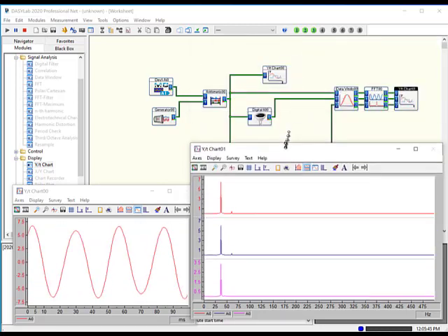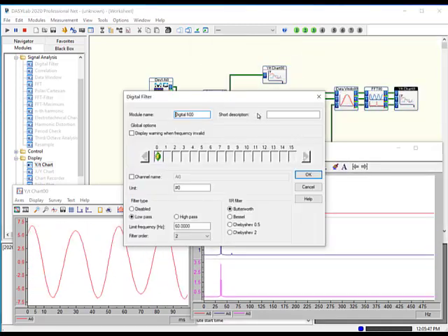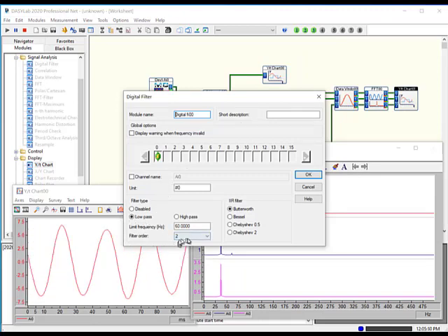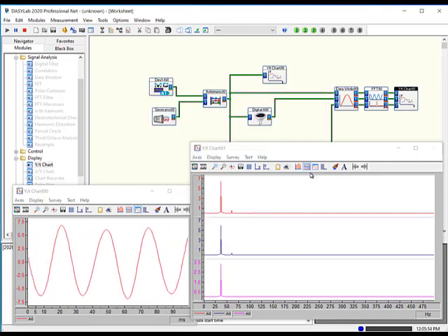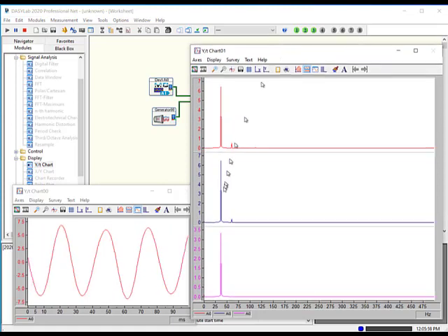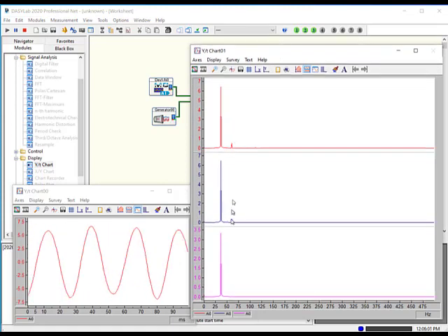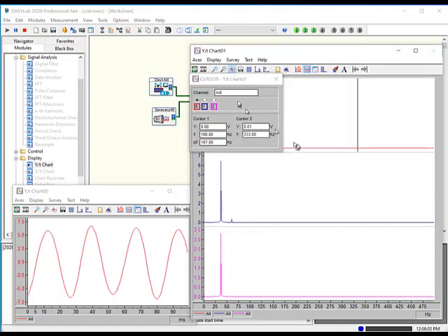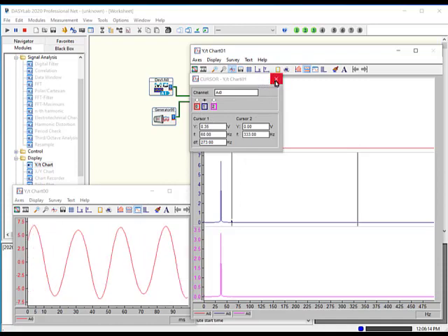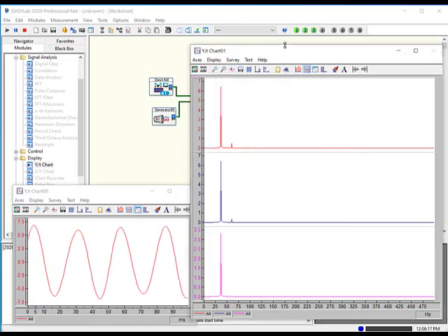One of the things you can do while you're running is modify the digital filter. So it's a low pass filter. I'm going to make it a stronger filter by going all the way to a filter order of 10. And when you do that, you can see that there's still some energy left from the 60 cycle signal. Look at this with the data window. The amplitude is not much diminished from the data that we're generating. So filtering failed.